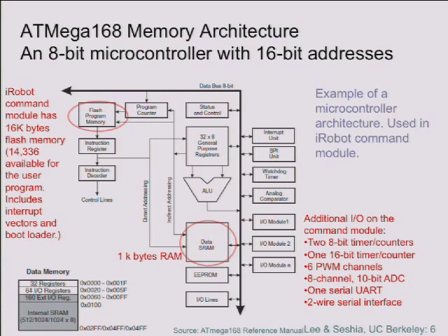So anyway, here is a map of the data layout. And it shows that the addresses are 16-bit numbers. This is an 8-bit microprocessor with 16-bit addresses. What does that mean, to be an 8-bit microprocessor with 16-bit addresses? Yeah. The data output is 8-bit, but then we have memory of 2 to the power of 16.